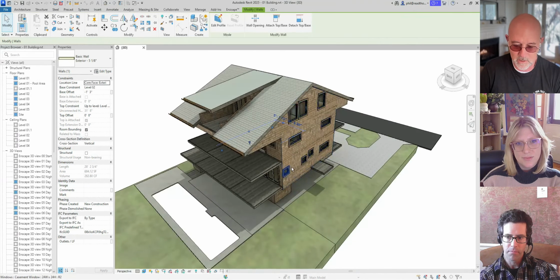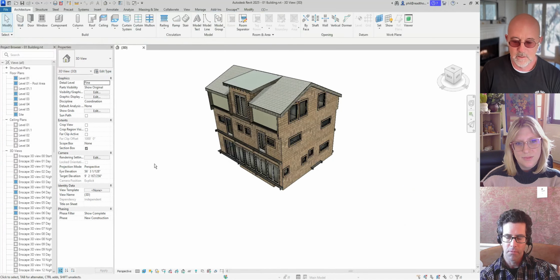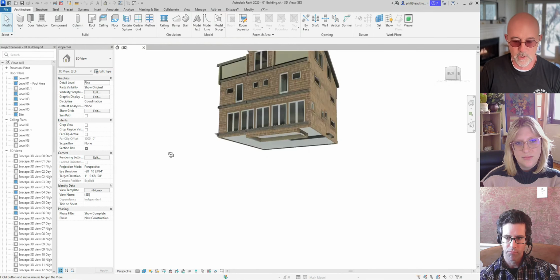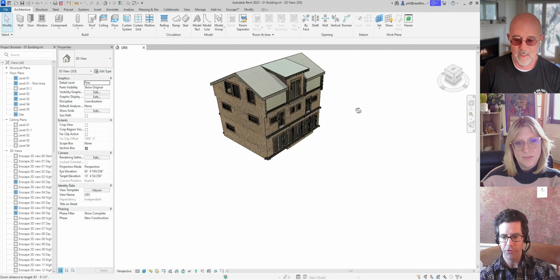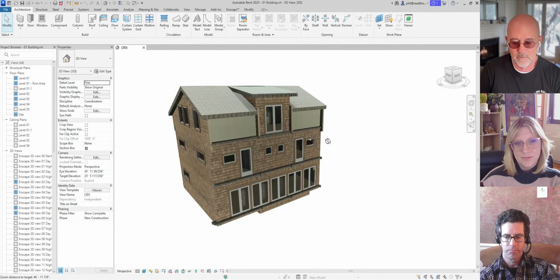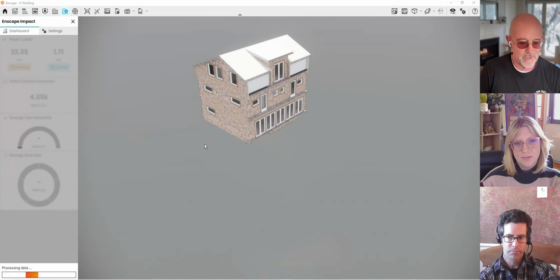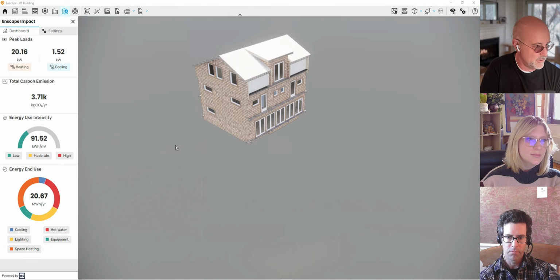So we'll grab that piece and that piece. And then I've got a shortcut that builds a section box. And that's really all that we care about, because that's going to turn off that storage room underneath. It's going to cut the shower. It gets rid of the decks, and it's your conditioned spaces. It's also turned off any furnishings or fixtures inside. We don't need those. And now what happens? It's going to reprocess the data and give us a number that's, oh my gosh, 20.67. So 21 times 0.11 times 1,000 divided by 12.